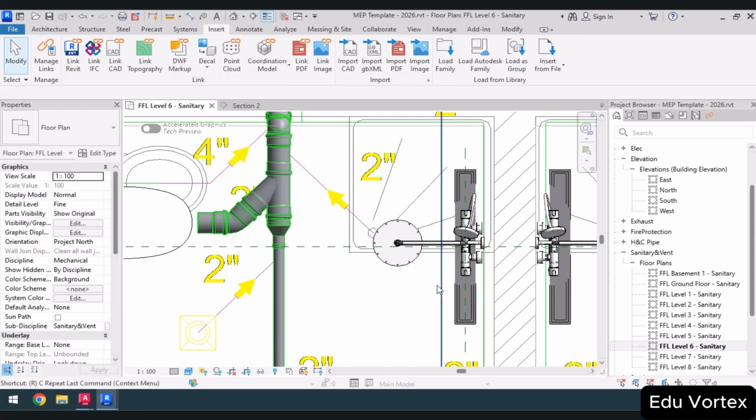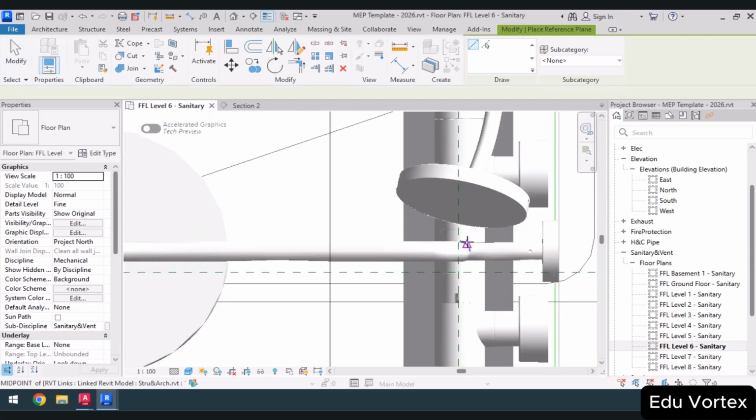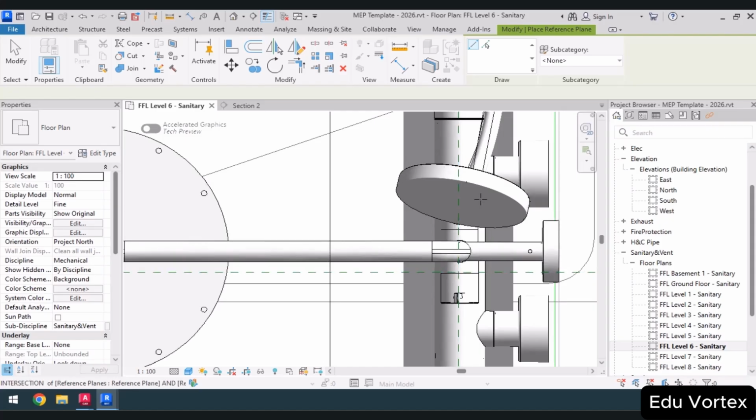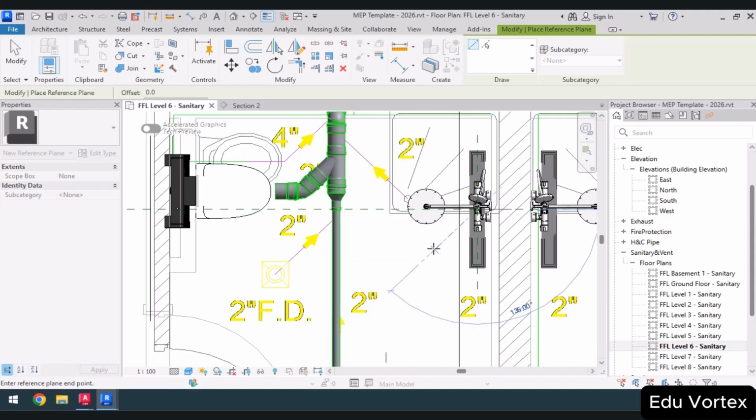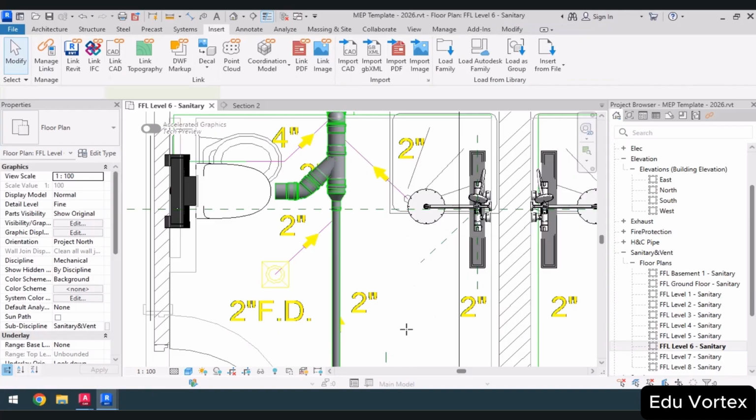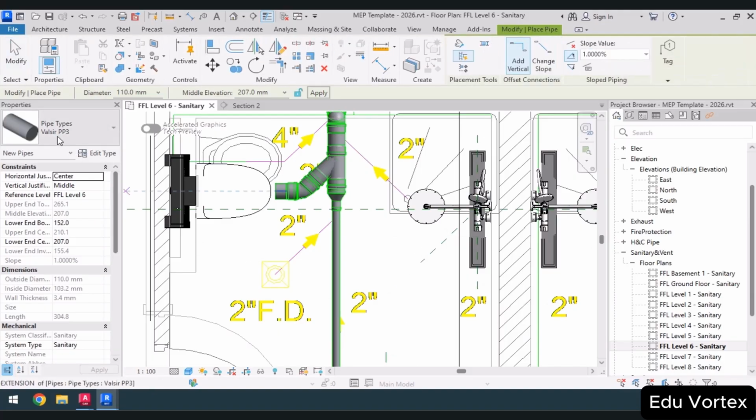So those are necessary for me to accurately determine where my pipe connection will be located without needing to realign them later. So I clicked at the 45 angle for this connection. Now I can use the pipe command and check my 3 items: connection type, which should be correct, size, which should be 50 millimeters or 2 inches, and height. What should I do? So I need to click in these areas, but the slope is not clear to me.